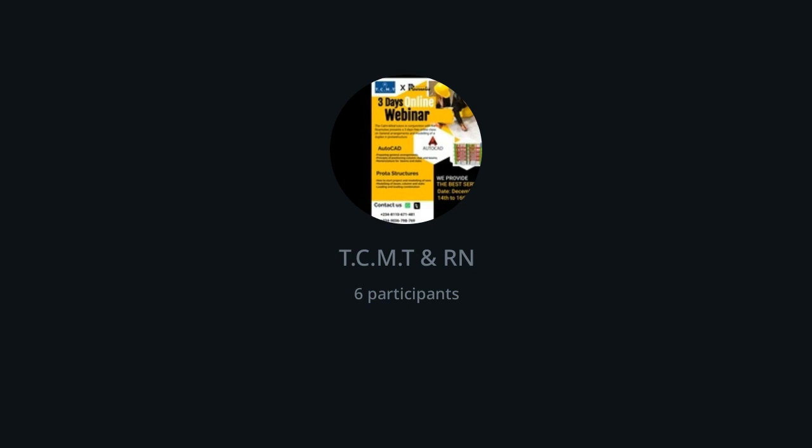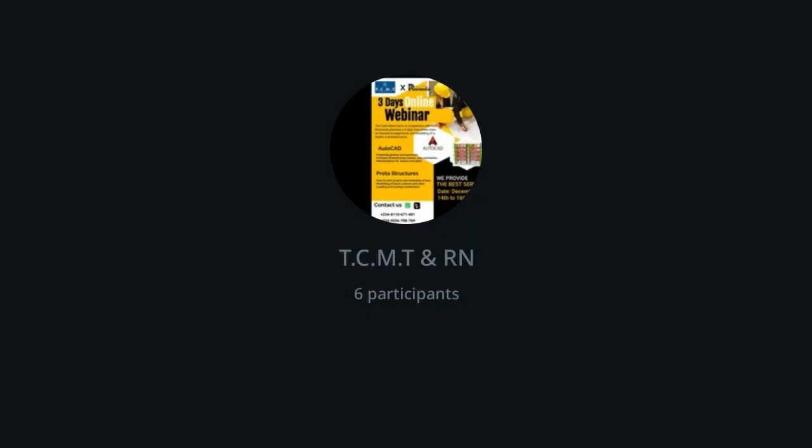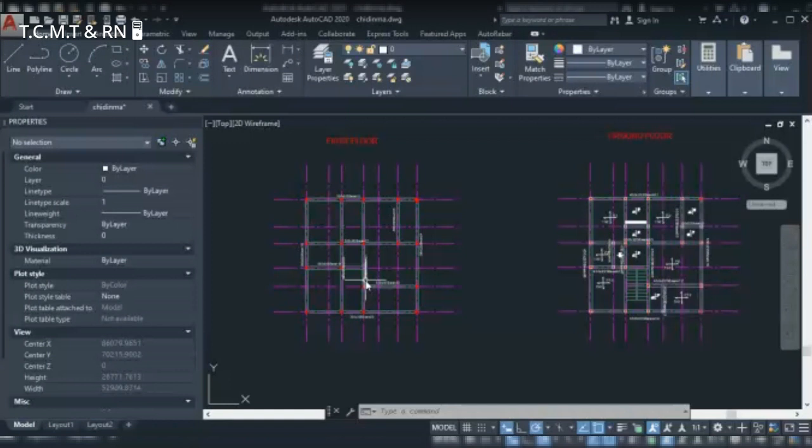So from what we can see here now, we have a beam that carries a slab, and we have a beam that doesn't carry a slab. So this one is carrying the slab, and this one is not carrying a slab. So there's a nomenclature to represent the beams that are carrying slab and the ones that are not carrying slab. From your engineering drawing, you know that anything hidden or anything under something will be represented with a dotted line.